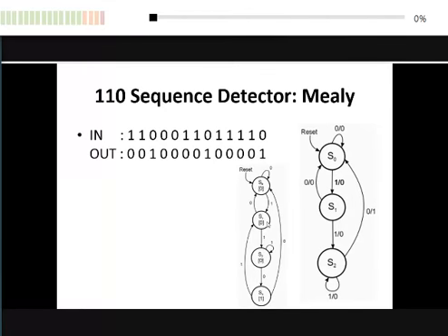Look here. Normally at S0, S1, S2, they are the same, if you look carefully. Remember, in Mealy, it is input, output, input, output. So 1/0, because the arc is 1. The S1 to S2 arc is also 1. That's why you get 1/0, here also 1/0. Now the problem is here, S2. There is some kind of art to determine where it should go, but you can analyze it logically, okay?